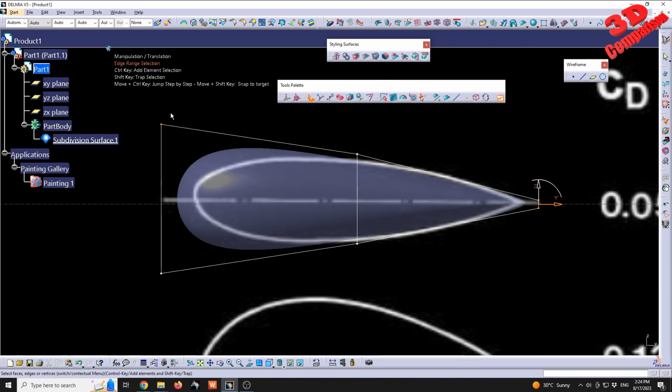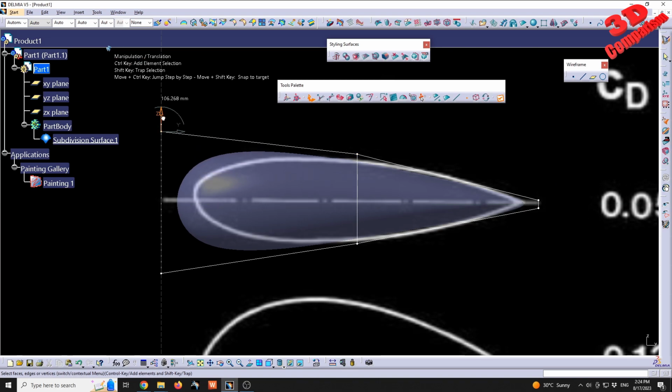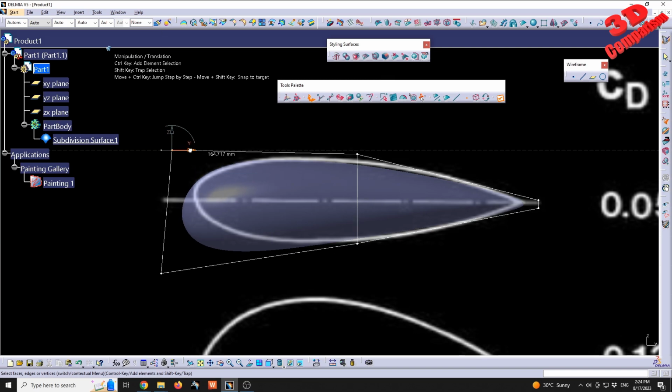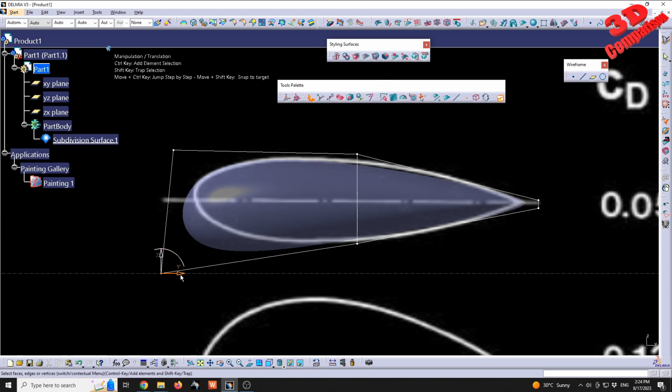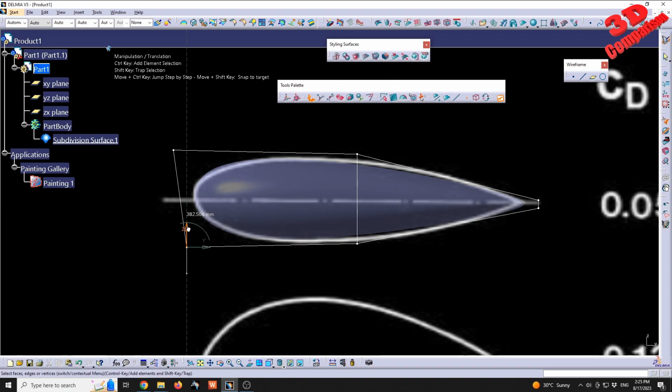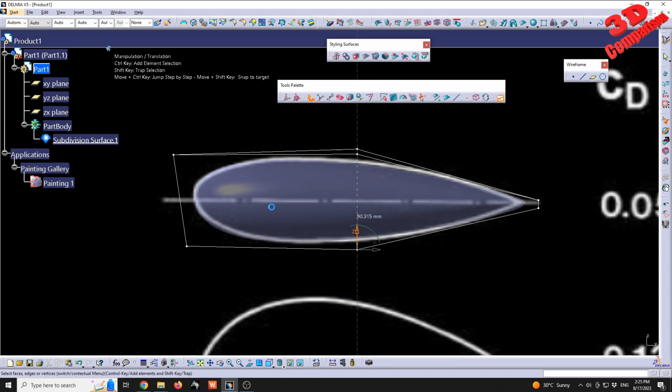And I'm gonna go to the front and I will select the 2 points at the top, and I will slightly adjust those as well, both on Z and on Y. You can also drag them directly on 2 axes, but I prefer to do it like this, only 1 axis at a time. In my opinion, I think that you have more control doing it like this. Okay, so this will be the first shape, and we still need to slightly adjust this at the bottom.